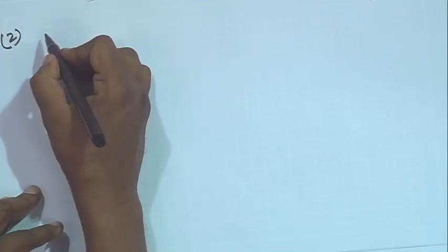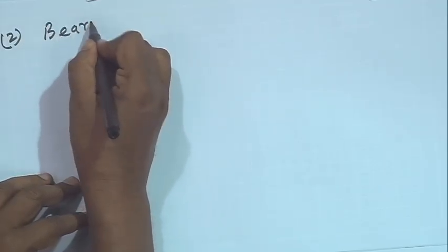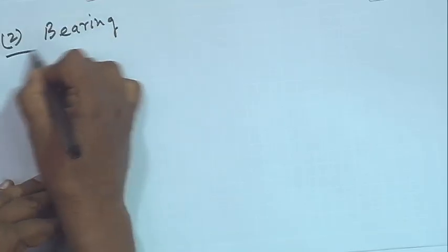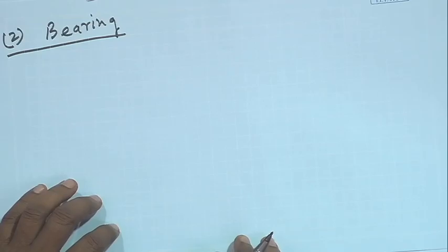We have seen first that bolt in shear. Now, for bearing, as I told, the bolt may fail due to shearing effect and due to bearing effect, and the bolt may fail due to tension. Also, the joint may fail due to tension failure of the plate, that also has to be considered. So, how to calculate shearing strength we have seen.